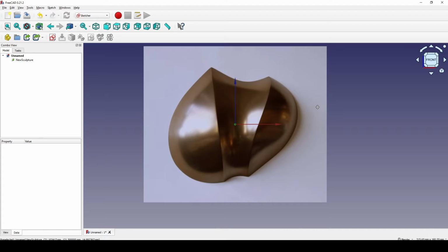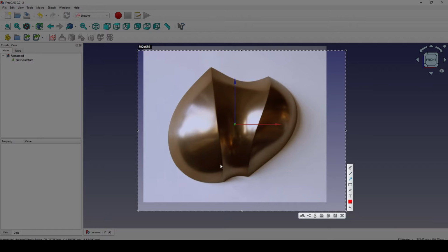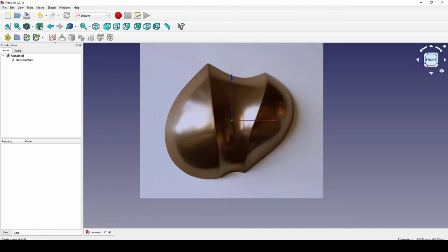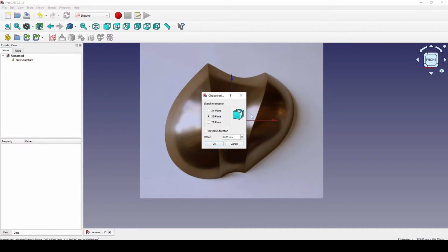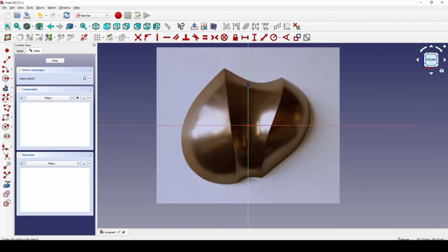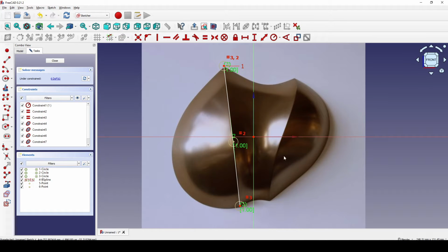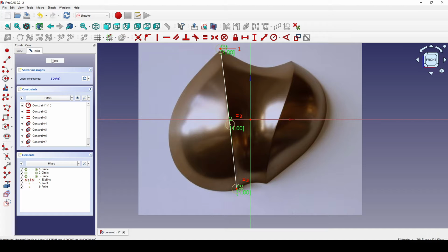Now I create a new sketch on the front view. I want to sketch in this curve and this curve. Create a new sketch, front view. Okay. And create freehand display. Sorry, create display. Let's put 3 points in here. Okay, something like this. And I close that.